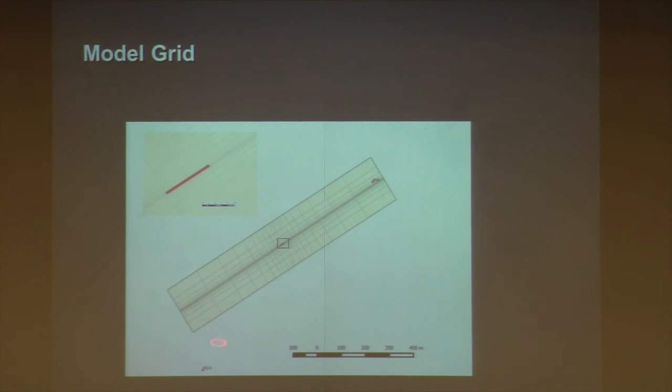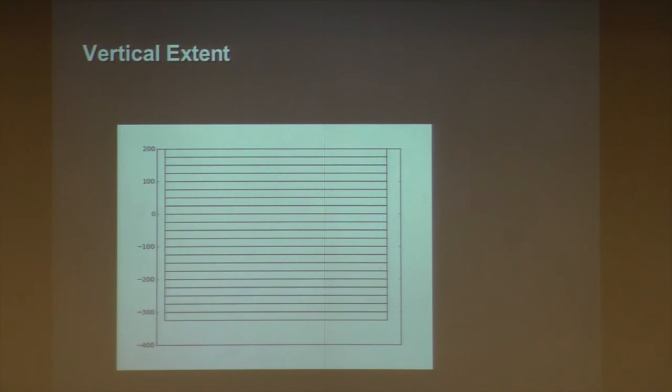So we constructed a model grid. So this model is about 1,000 meters in length, about 100 meters that way. We have very fine resolution around where the springs are. I think this grid block is about 1 meter in size. We're modelling, as I say, just the flow through the cap rock, which is about 500 metres thick.